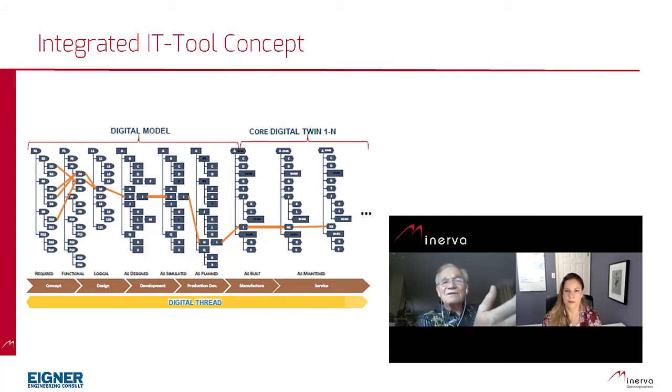Then you start with the M-BOM, the manufacturing BOM, the manufacturing process plan, maybe a plant simulation, assembly line simulation. During the product life cycle, you are generating thousands of information. It's a very big, we call it semantic network. It looks like what the spider is doing, this net. You hit one node and you get all the other information together. Digital thread. The digital connection.